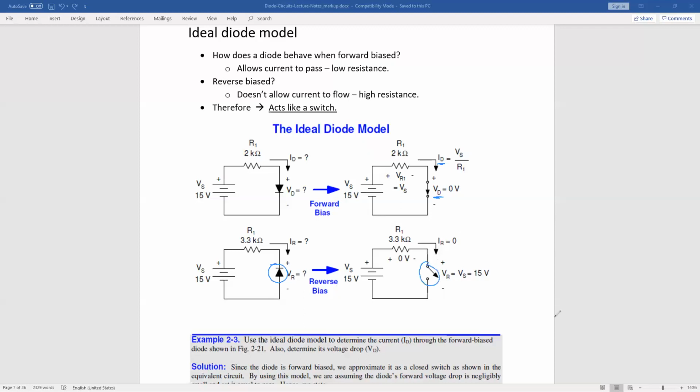So this is acting like an open, and in an open circuit, whatever voltage is across here has to be equal to the voltage source. It's not going to have any voltage dropped across this resistance, because compared to the basically infinite resistance of an open circuit, this is a very, very tiny, negligible resistance. So all of that voltage is going to be dropped across the open right here. So this reverse bias diode voltage is going to be equal to Vs.